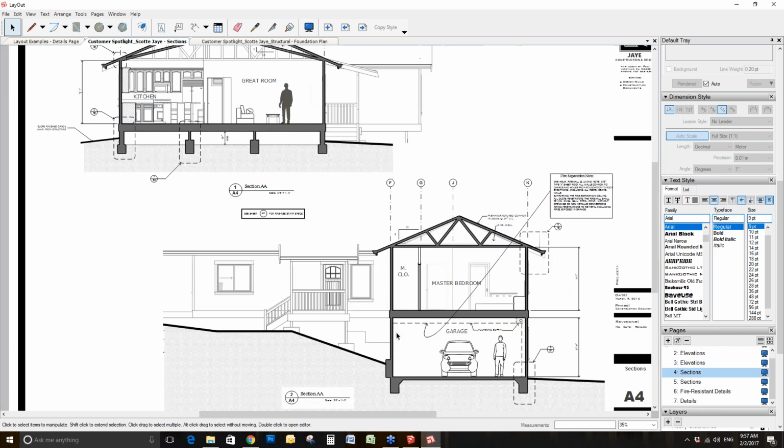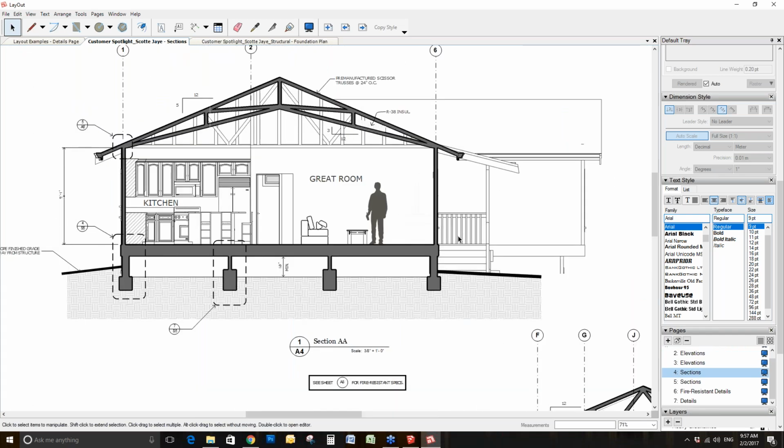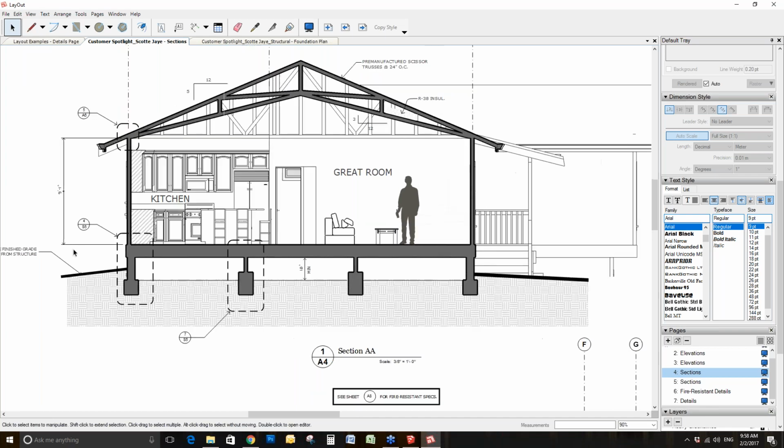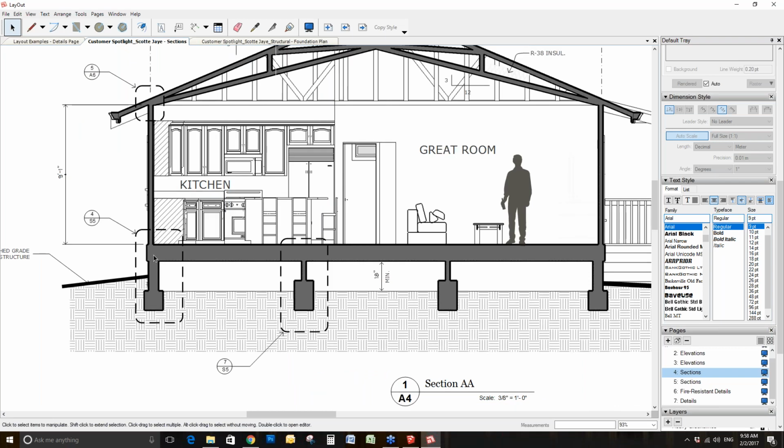You can do sections in two different ways. You can do them in North America. Sections are often done with just a solid color because, depending on your scale, unless you're very zoomed in, you can't actually see a lot. I actually agree. For example, in metric, 1:100, which is pretty standard for sections, what's the point of spending the time? When you print it, you don't see anything. So I actually like this idea, and then the call outs are what is actually going to detail the project.